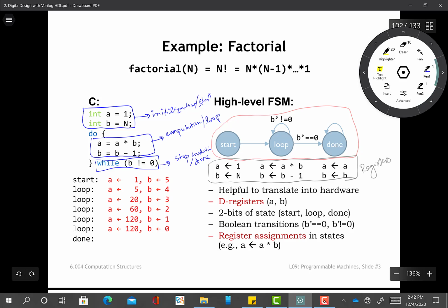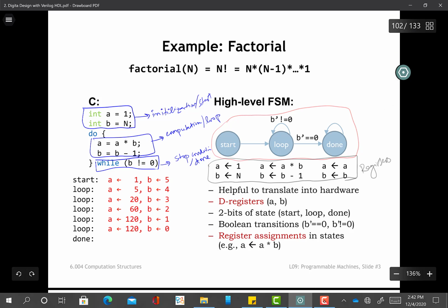So all we need is two registers. From where I know this: in order to store A, I need a register, and in order to store B, I need a register. So these are my physical registers which I need in order to compute this in hardware. Then I need, for example, this multiplier and subtractor and this logical operator. These are all the things that I need.